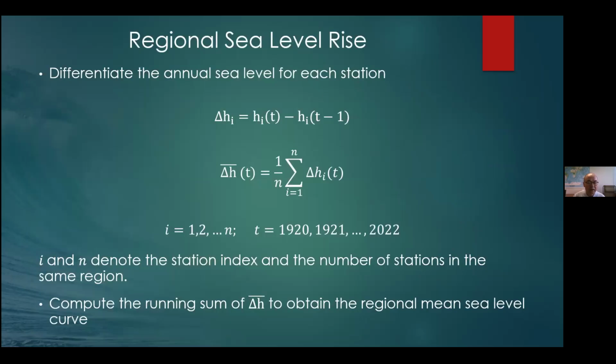We compute the annual mean sea level based on the monthly mean data. To compute the regional mean sea level curve, we first differentiate the annual mean sea level data for each station, because different stations use different reference sea level.